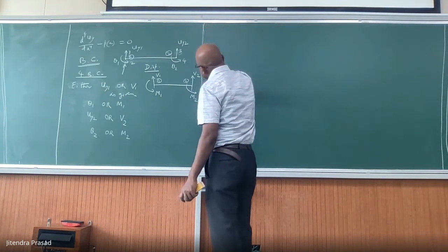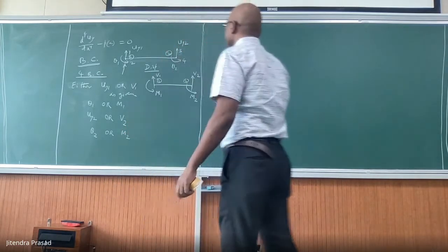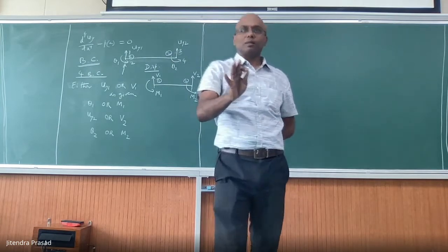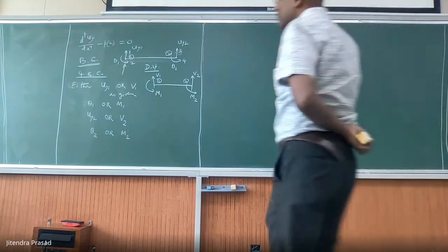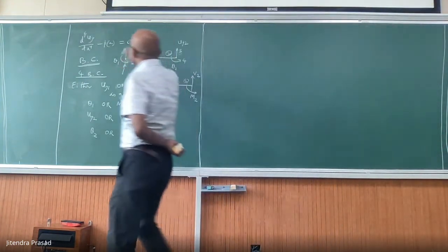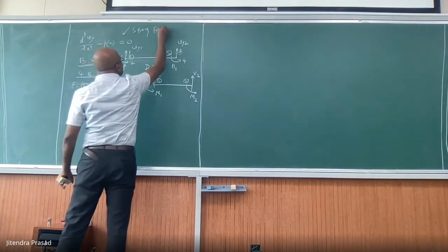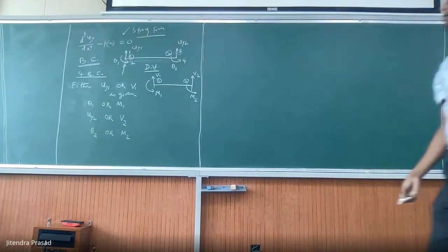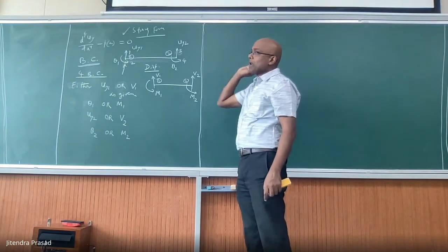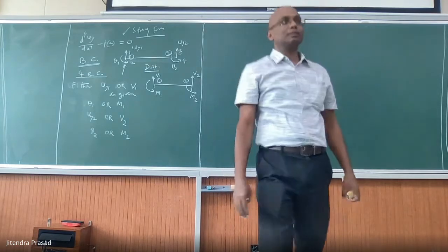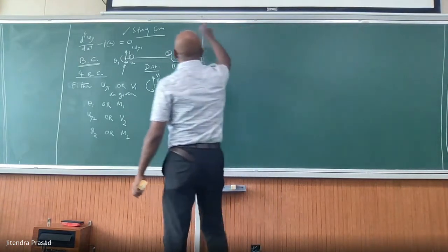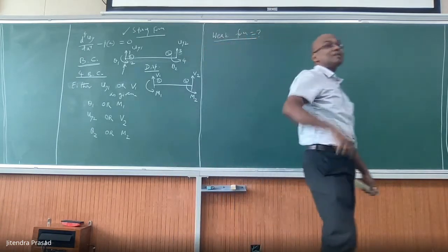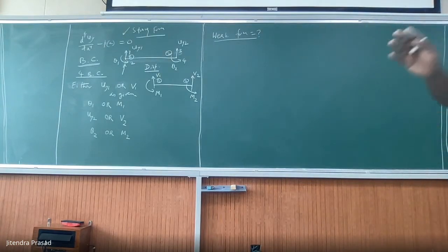Now today, what we are going to find out is the usual way of solving a finite element problem. The first thing you do is, this is a strong form. A strong form is basically the differential equation along with the boundary conditions. In order to apply the usual approximate methods, for example the Galerkin method or Ritz method, first you have to get the weak form. So first we have to find out what the weak form is, and from there we solve. So that is the usual method you have to adopt.